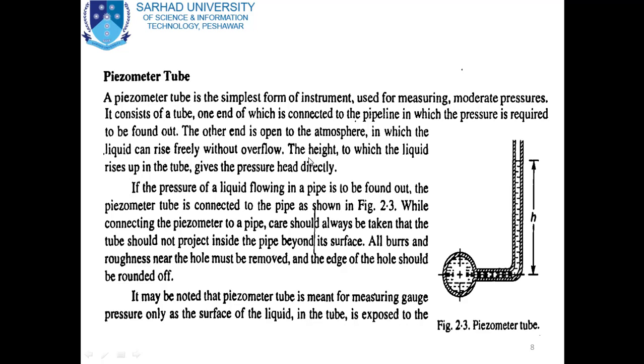The height to which the liquid rises up in the tube gives the pressure head directly. In the case of piezometer, the end which is open to the atmosphere, in this tube the liquid can rise freely, and up to which height the liquid rises, this will give you the pressure head directly.